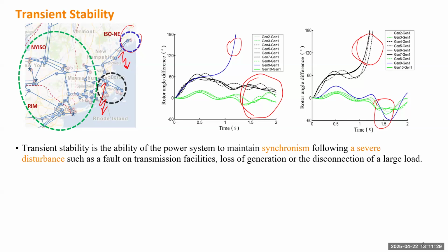You can depend on the balance of load. You want to decide whether to reject some generation or trip some load to maintain the rest of the system operating at 60 Hertz. But for the second scenario, you may not be able to trip everything in that group. If you cannot save the system by load shedding, you may have to do islanding, right? You have to form an island for that out-of-step group of generators to operate on their own. That is a more critical condition.